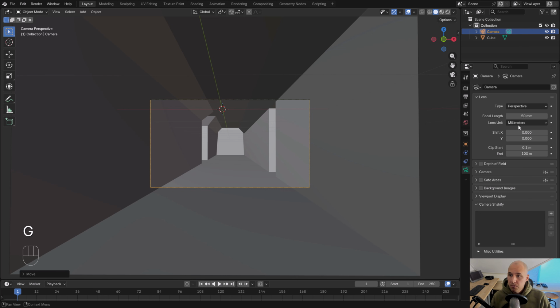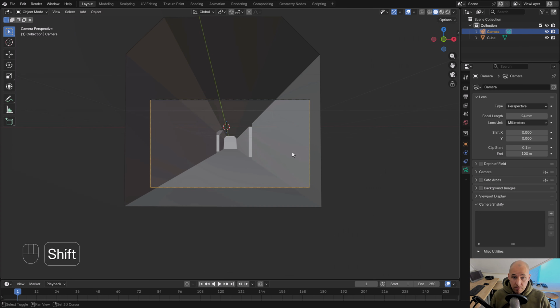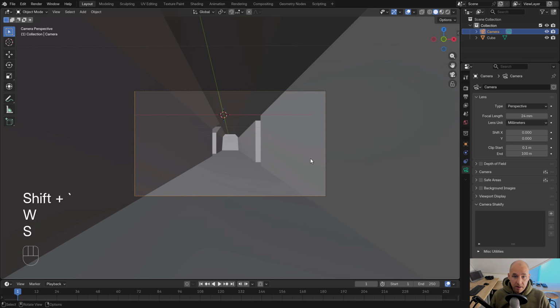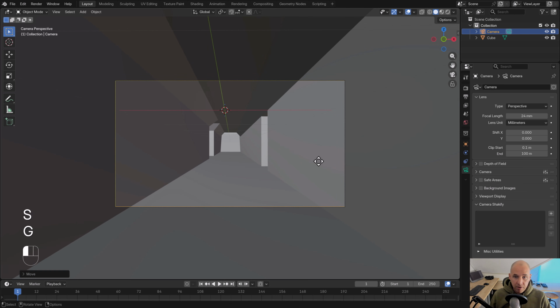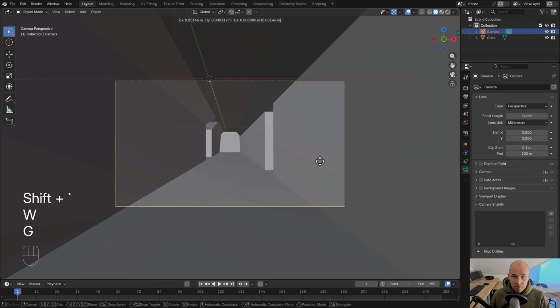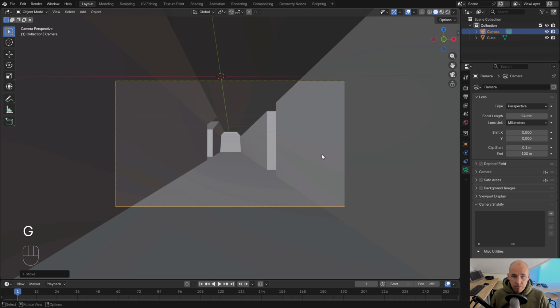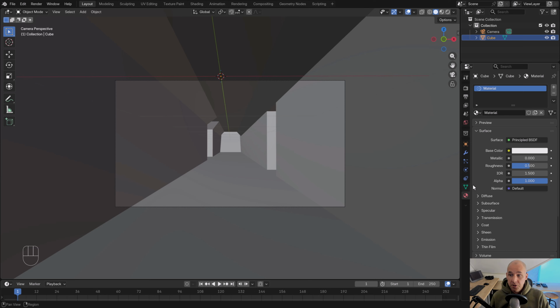At this point, I also like to change the focal length, starting with 24. Now we can move forward, something like this. We have to find like a nice position. Okay, so far so good. What I'd like to do at this point right now is focus on the materials, and we're starting with a concrete material. So we go to the material editor and concrete layers.